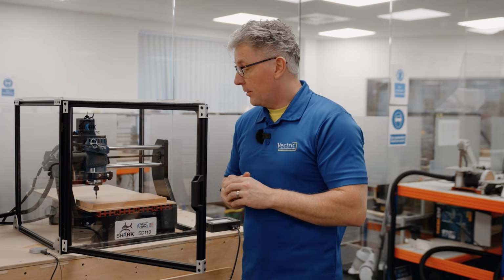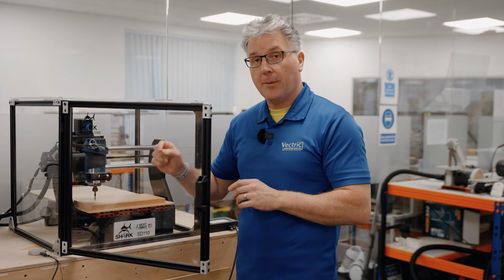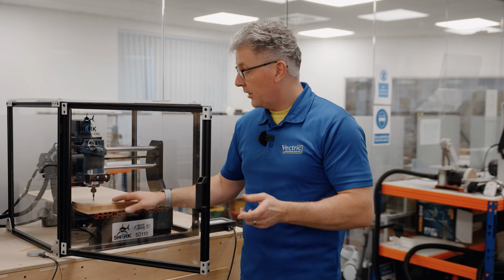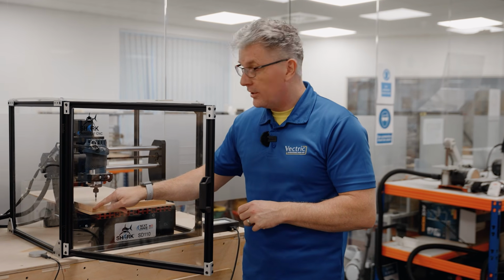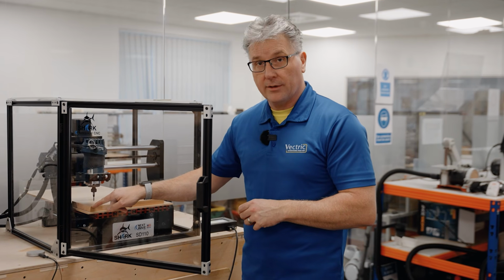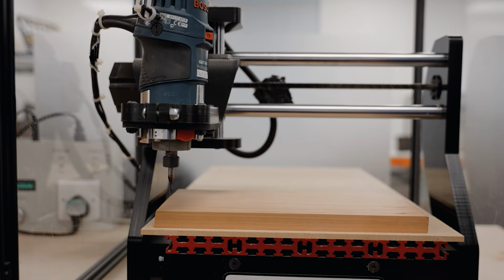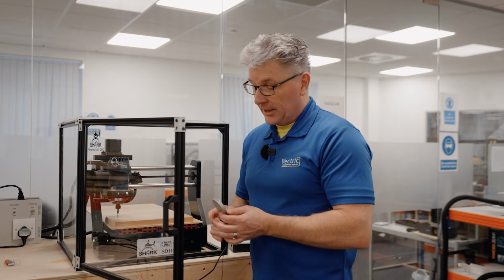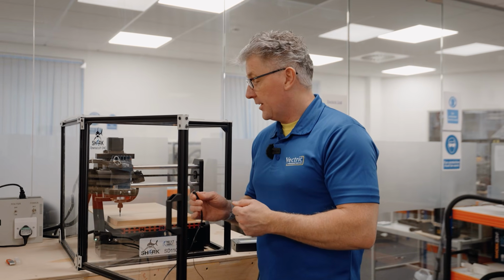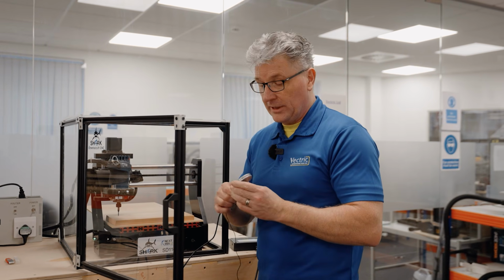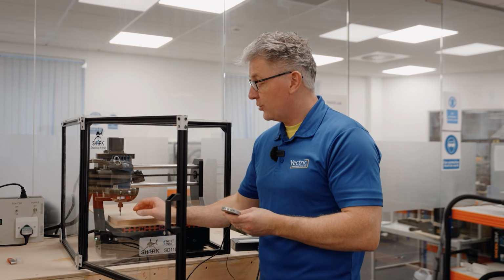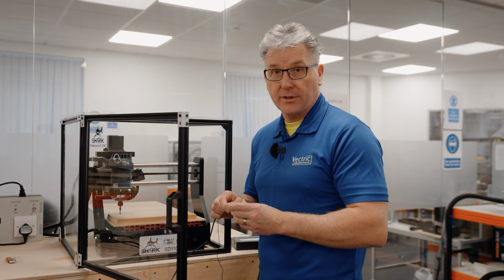Okay, my next step now is to set my tool over top of my 0 position of my material, just like I set it up in the software. So my XY0 is going to be right here on the corner. So let me do that now. So now that I have that lined up as close to the corner of my material as I could get it, I'm going to go ahead now and zero my tool using this 0 plate, and that way the software or the controller will know how far away the tool is from my material.